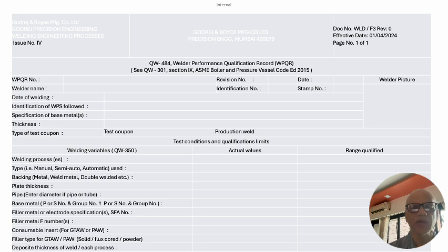In addition, the ideal conditions we can maintain on PQR as specified in the WPS, the root gap, root face, included angle, set-in or set-on nozzles, pipe to pipe, tube to tube sheet, or any other fillet, the setups which are going to come, the constraints and the difficulties or the practicability of the joint are going to come when we start on the equipment.